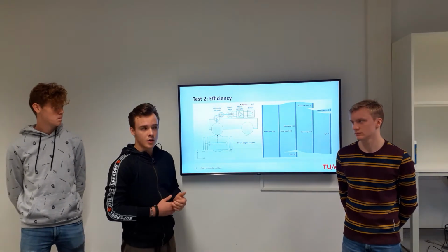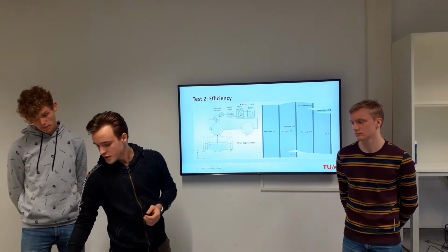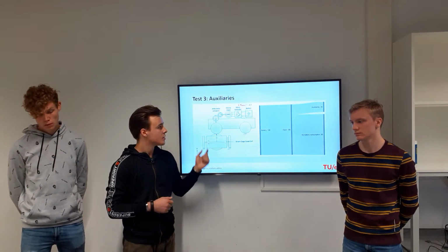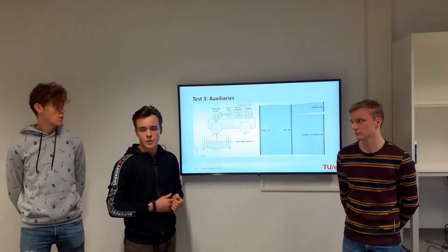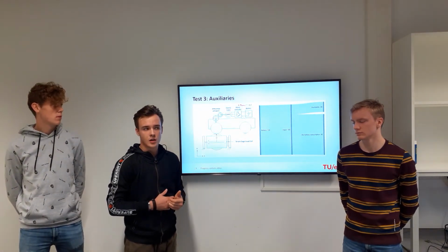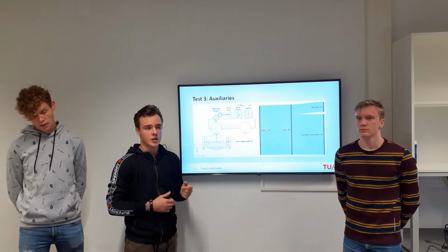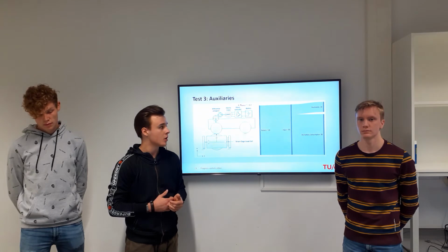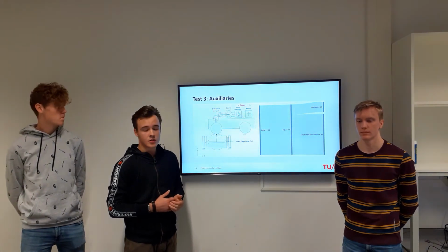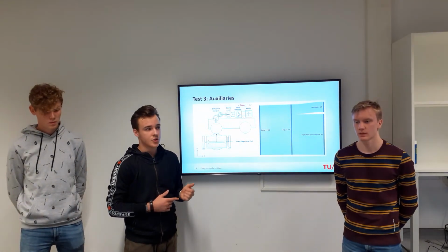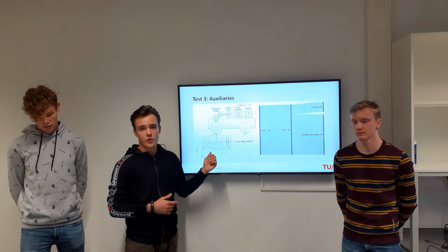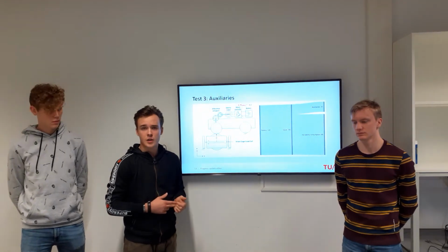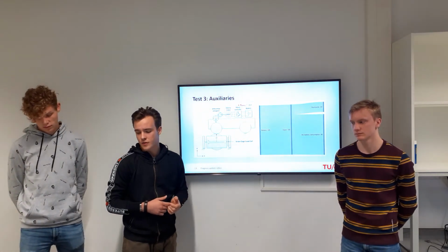So we know the total efficiency, and the third test will make the efficiency even more correct, because with this test we will calculate the auxiliary power consumption, and if we subtract the power lost due to the auxiliaries, we know how much power is lost elsewhere within the drivetrain, and so we have the total efficiency of the car, and we can make a proper tank-to-wheel analysis of the vehicle.